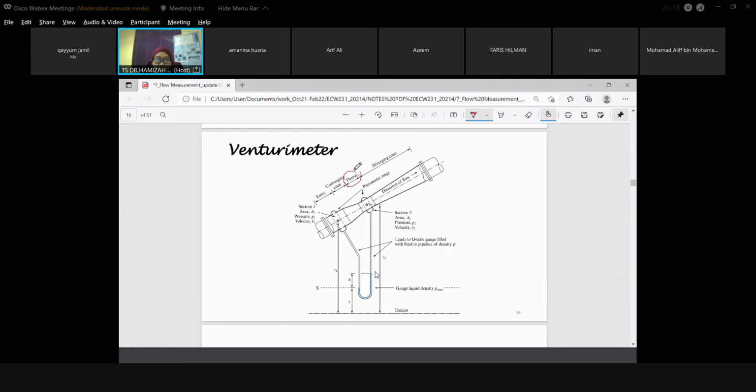So when you see the word throat in questions, throat is referring to the smaller size of the pipe. The larger pipe, we just call it the pipe. The size of the pipe is, for example, 50 cm. The velocity at the throat, so throat is referring to the converging, or constriction, of the pipe.